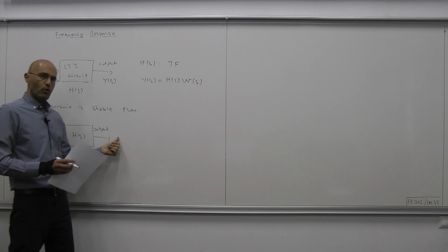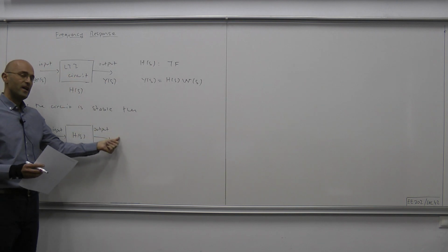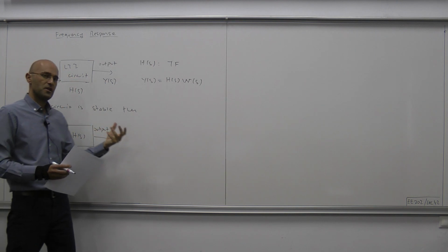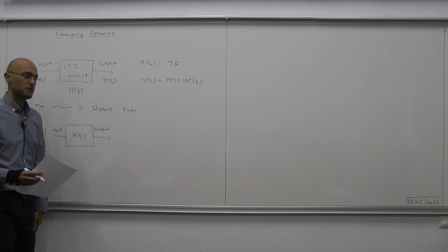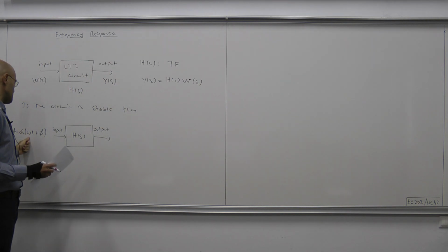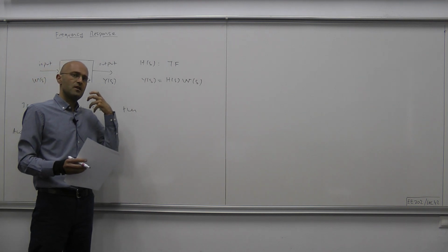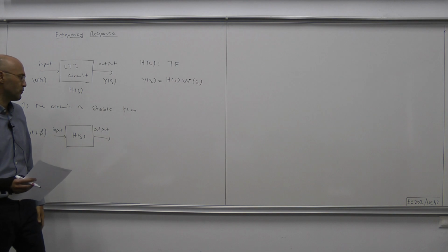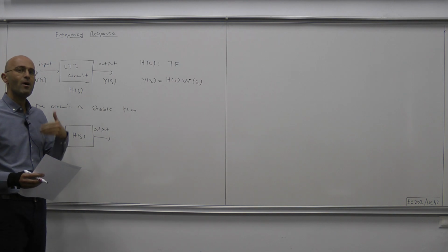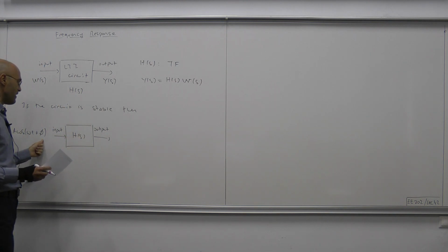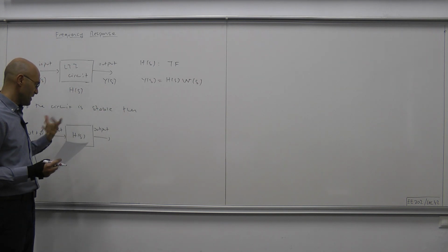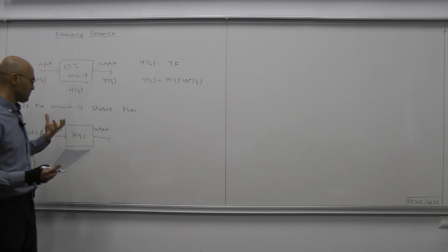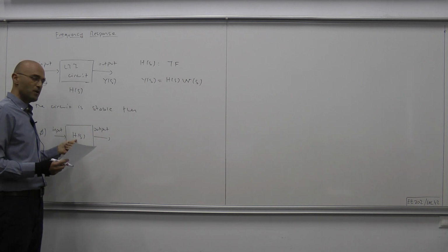First of all, since the circuit is LTI, at the output in sinusoidal steady state we will again see a sinusoidal signal oscillating at the same frequency as the input. That is, the frequency of oscillations for the output will be omega. Now, how about the amplitude and phase of the output? We've seen that they are directly related to the transfer function.